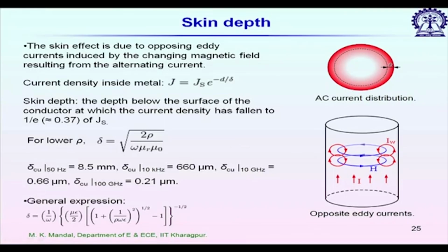Since it is utilizing a very thin layer, surface resistance will be very high at millimeter wave frequencies. The surface resistance is so high that the metal will be very lossy. In fact, at optical wavelength, the frequency is so high, we can't use any metal at all. That is why we always use dielectric material in optical fiber.